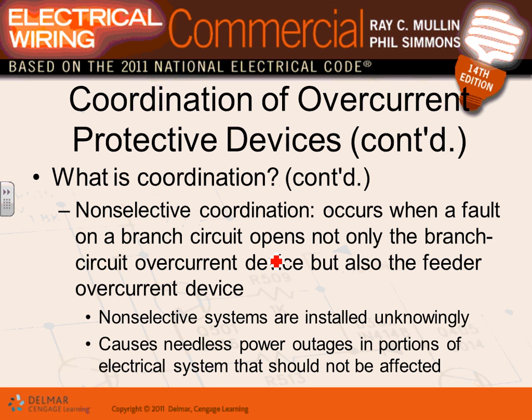Non-selectivity is very simple. You change the ballast right here, and the main of Dunwoody trips. Now everybody in the whole college waits until the electrician walks over, goes to trip the circuit breaker, and resets it. Is that bad news? Do you see how bad that would be? They call it a non-selectivity system. It provides needless power outages in areas that are not affected.